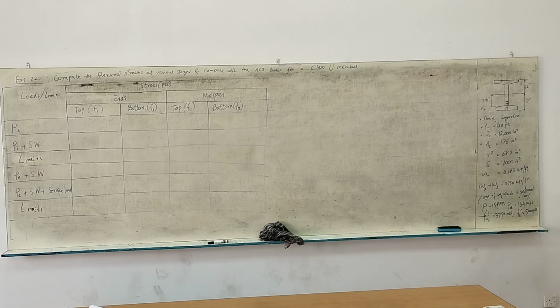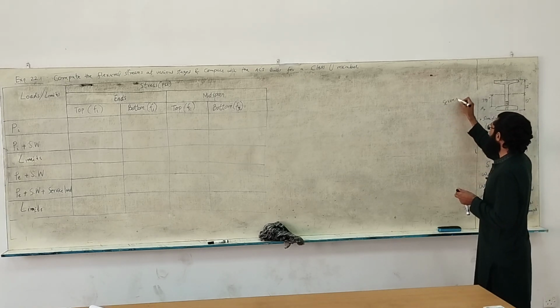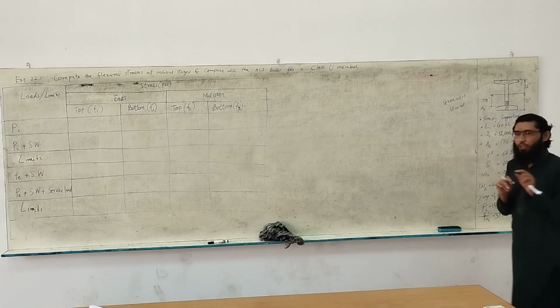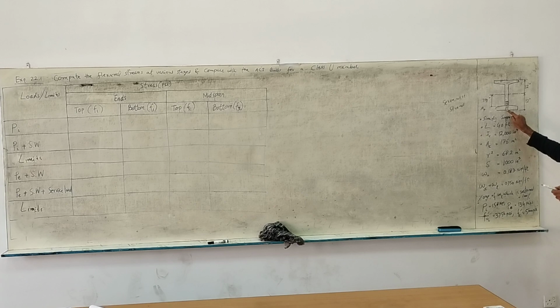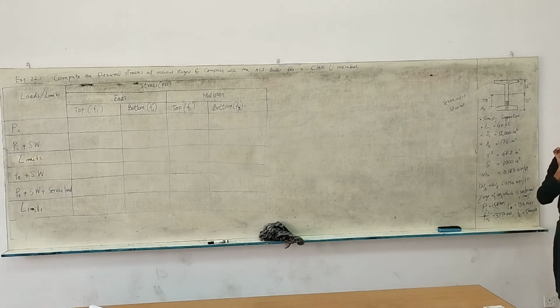Now this strand is itself composed of 7 wires and is also known as a 7-wire strand. Okay, so each strand is itself composed of 7 wires and there are a total of 10 strands over here. These are all the same diameter, so they all have the same cross-sectional area each. Their own centroid is at this level, the center level.